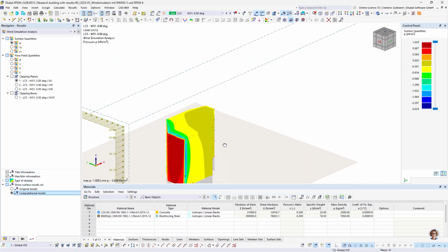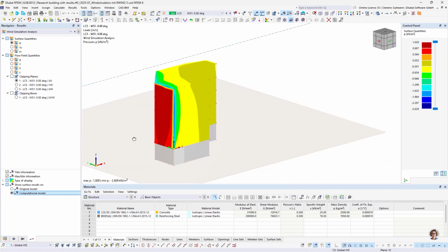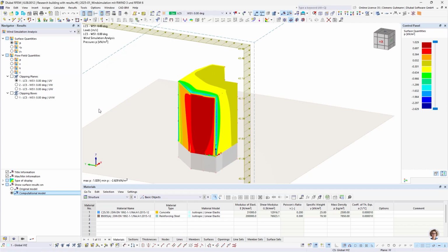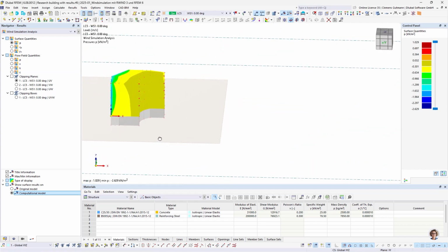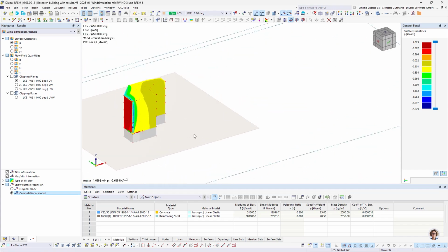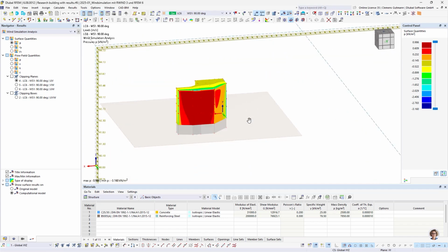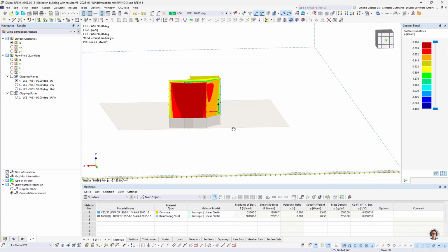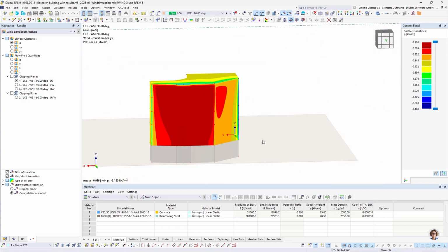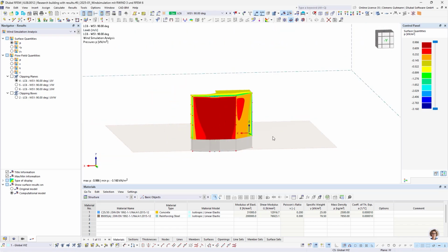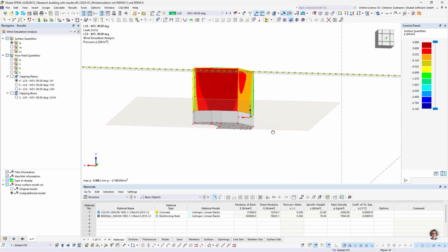And we can here now inspect the pressure, the wind pressures, and also the pressure coefficients, as well as the flow field quantities, whatever we want to know, in the different directions that we analyzed, and now can get a better idea of how the building reacts to wind exposure. And as you can see, the terrain that we set in the beginning is now displayed,